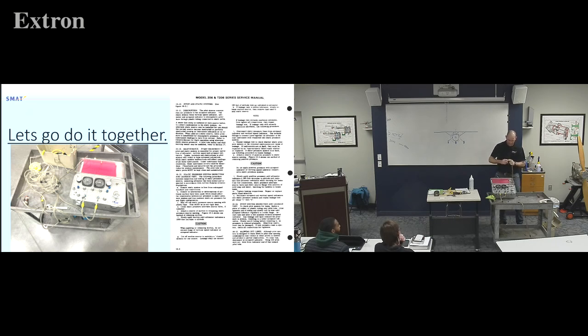There. Like you will on the aircraft, and we'll do this in a minute. If we have both of them plugged, get myself back up because I just lost my 1,000 foot. There we go. It moved, or I can have my cross feed open. The cross feed just neutralizes out across this. So I've got to go a little bit more because now I'm actually testing both systems. There's my 1,000 foot, and I wait for a minute. As long as it doesn't move in a minute, we're good to go.